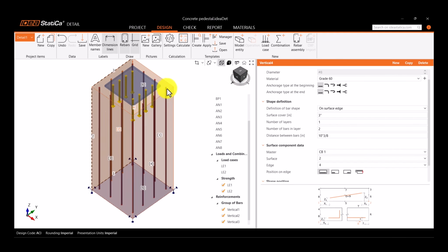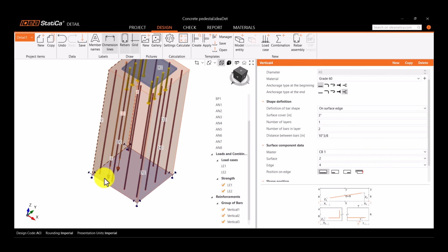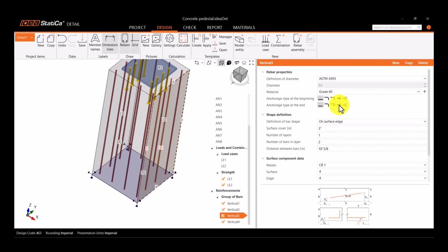At the top, I'm going to use basic anchorage. So there is no kind of restriction between this start of the anchorage to the concrete, but at the end it's going to be continuous. So this means this is continuous through that surface, so it's the same. It's perfectly bonded, okay, to this area. So I'm going to do the same for all of them. All the groups.